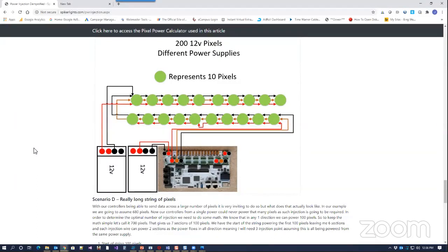Yeah, you can send from a different power supply. I would say no. From the same power supply, yes. Resistor and regulated. Yesterday, RGB man said regulated pixels will pop if power goes the wrong way. I've run both regulated and resistor, and I've never had an issue. Yeah, because power is typically going to be bidirectional, as long as your grounding is right and you have your grounds tied together. A lot of that is because your data is also dependent on having a good circuit. If you don't have a clean circuit, you're going to see data issues as well.